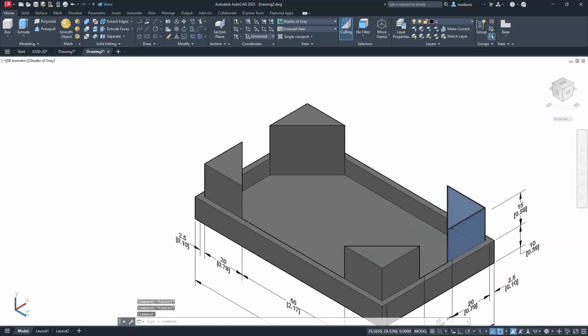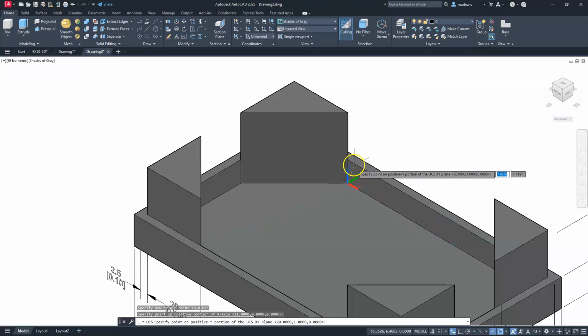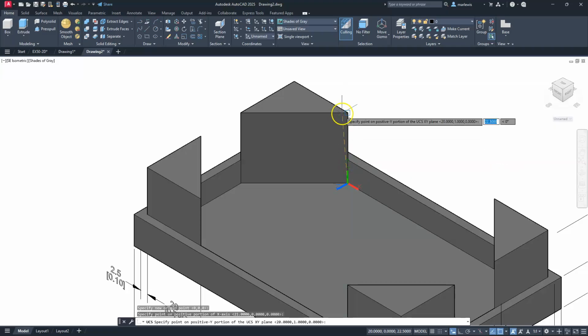All right, our final dimension that we need to place here is basically telling it how far it is, or the depth down here to the bottom. And we're just going to simply do that by placing a dimension along this back face here. All right, so the same principles can apply. If I choose this 3-point here, I can go from this endpoint, and then I can go to that midpoint and somewhere up along that endpoint should be fine.